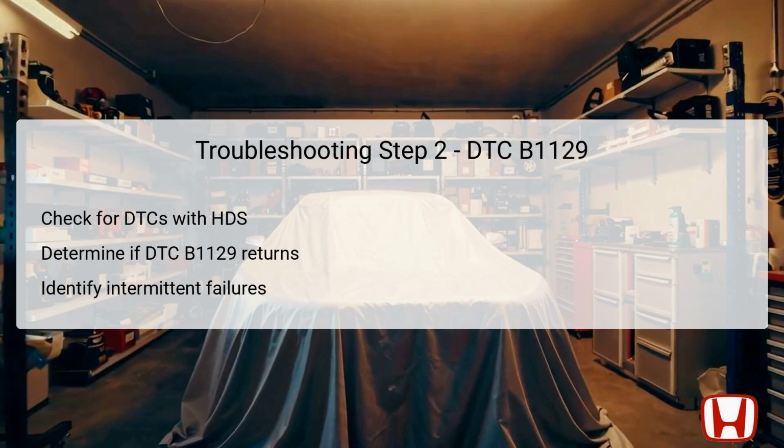If the DTC does return, this reflects a persistent problem, likely related to the door lock knob switch or the interconnected wiring. Conversely, if the DTC does not return, it may suggest an intermittent failure where the system is currently functioning correctly. Identifying the nature of the failure allows for targeted troubleshooting and repair steps to ensure the door locking system remains reliable.